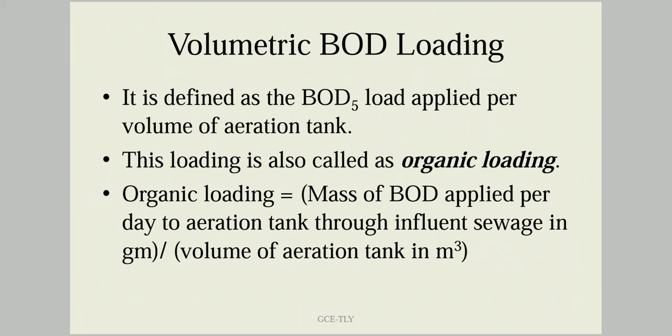Next is volumetric BOD loading. It is the fifth day BOD applied per volume of the aeration tank. So BOD5 per volume of aeration tank gives you the volumetric loading. This volumetric BOD loading is also called organic loading. Organic loading is the ratio of the mass of BOD applied per day to the aeration tank through the influent sewage, in grams, per volume of aeration tank in meter cube.